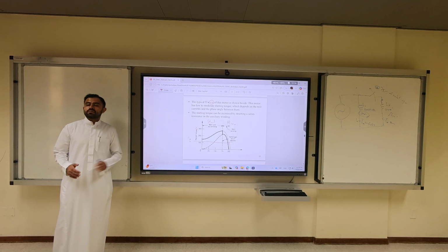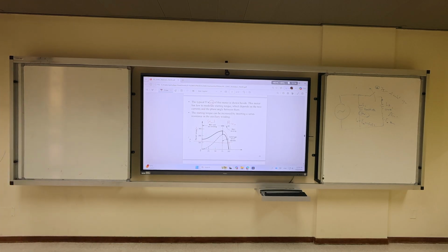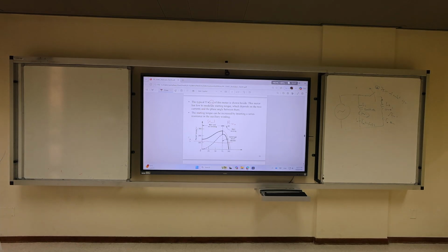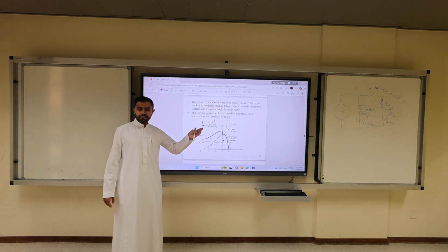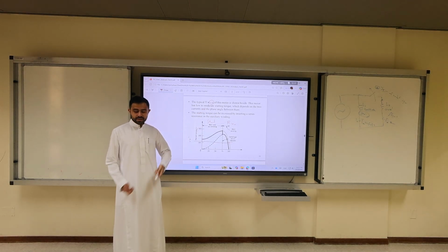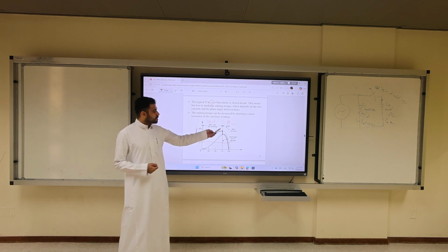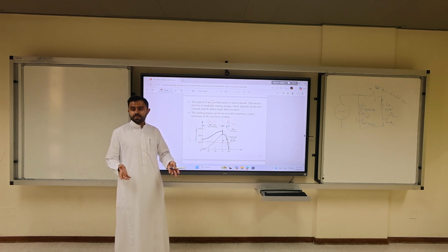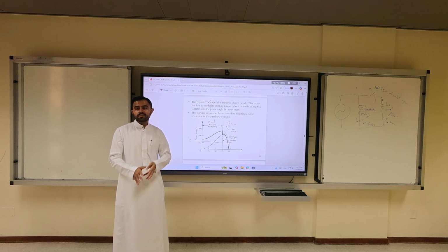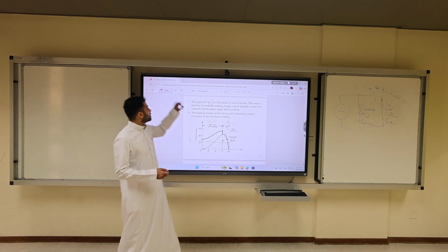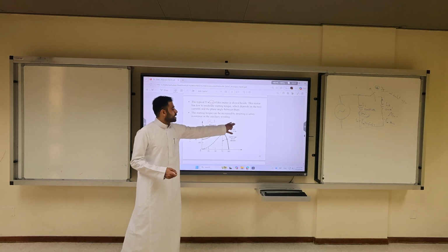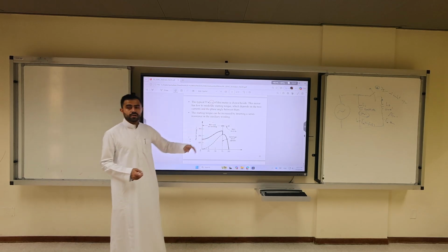But also why don't you use three-phase? Single phase are not efficient, but cheap. If you use two windings, I would say it will cause issues with the control because all the control methods are either for single phase or three phase. The other issue is this capacitor in your vacuum cleaner. If you keep it running, this capacitor might blow up. So it's about making your machine as simple as possible. So that's why we switch back to the main. Also, the curve control might be harder. But I can tell you, it's better to get rid of the other winding.